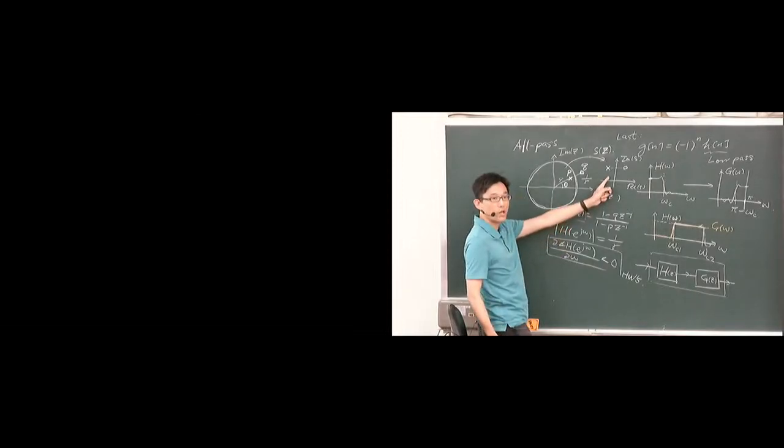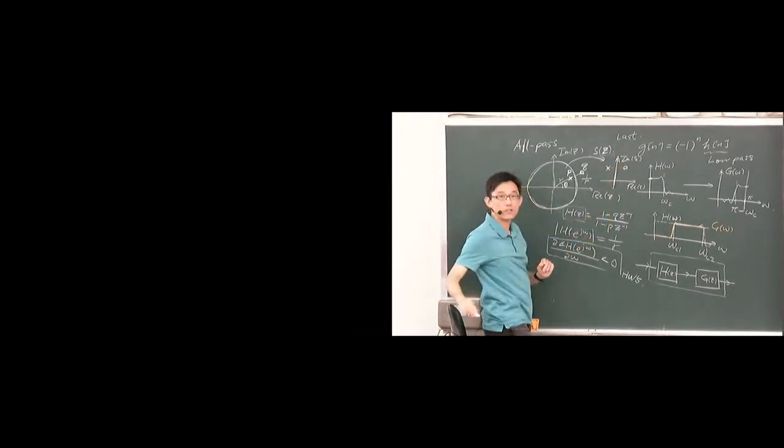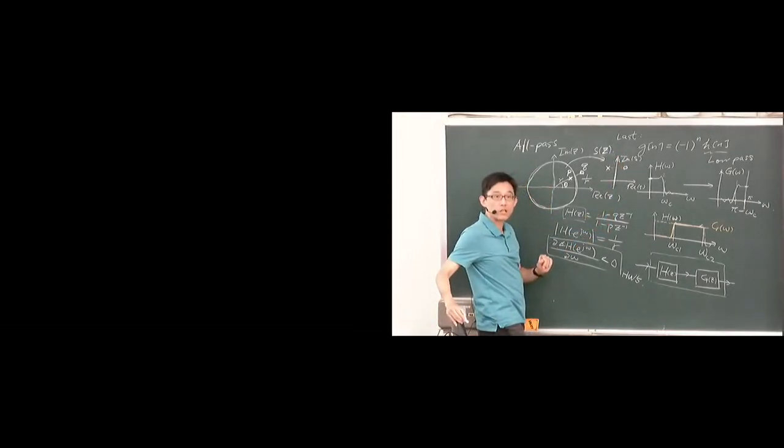So you can show that, as I asked you to. From there, you can also see why, when you go along the imaginary axis in the s-plane, the magnitude response is a constant, while the phase response always has the nice property that its slope is always negative. So that's kind of a preview. If you haven't taken a look at homework number 5, please do that.